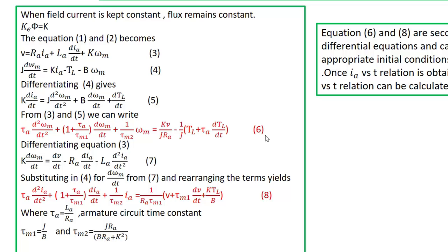That means from equation number 6 you can find how much time the system will take to achieve steady state in case of a starting condition, or 0 in case of braking conditions, or different transient conditions based on the initial conditions. And the transients you are going to analyze for this separately excited DC motor system.